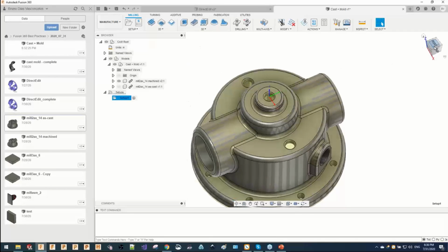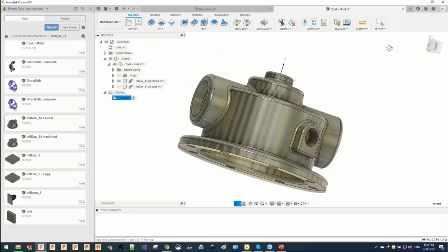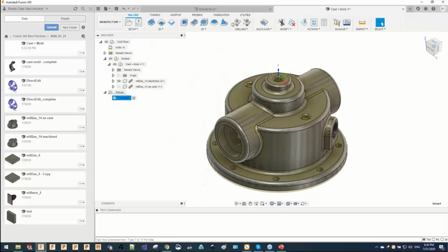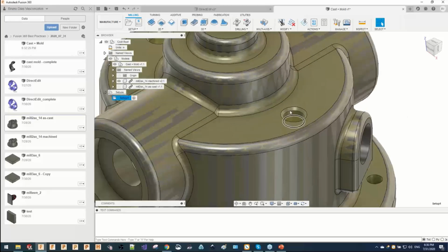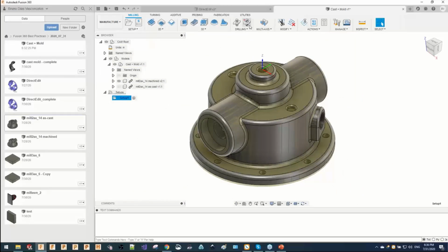If you normally deal with a lot of holes, you have two ways to make a hole. You can do the regular process and create a template. A template could be like 3 operations, like spot drill, drill, and tap, and then call that template anytime that you deal with the same type of hole.